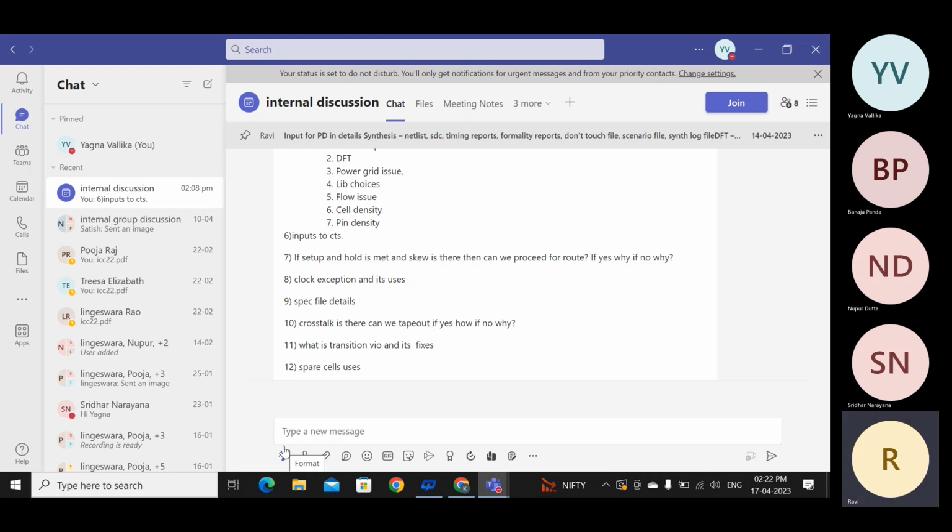And for an exclude, you want that clock tree, that particular branch, not to be balanced, or you don't really care about balancing that. Then you will exclude the branch, or exclude this clock, from any clock balance requirement.